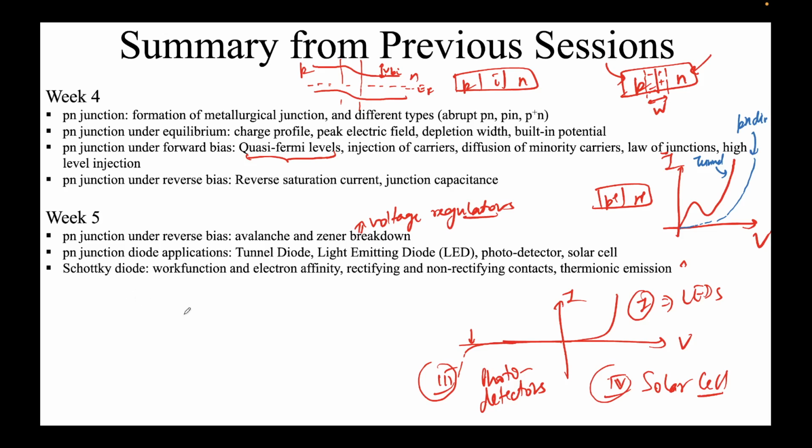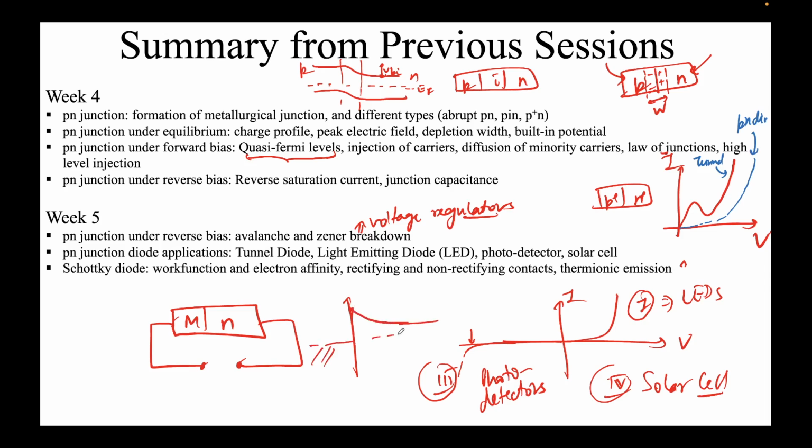And finally, we had talked about the Schottky diode. So a Schottky diode is nothing but your metal-semiconductor junction. So one side is metal, another side, let's say, N-type semiconductor. And now again the same analysis we had obtained. We saw its band diagram was a bit different. So this was the EF on the metal side, and depending on a certain entity called the work function, and so on. So we saw that this was the Schottky barrier that we had encountered, phi n. And so this is the N-type, this is your metal, dotted line is your EF.